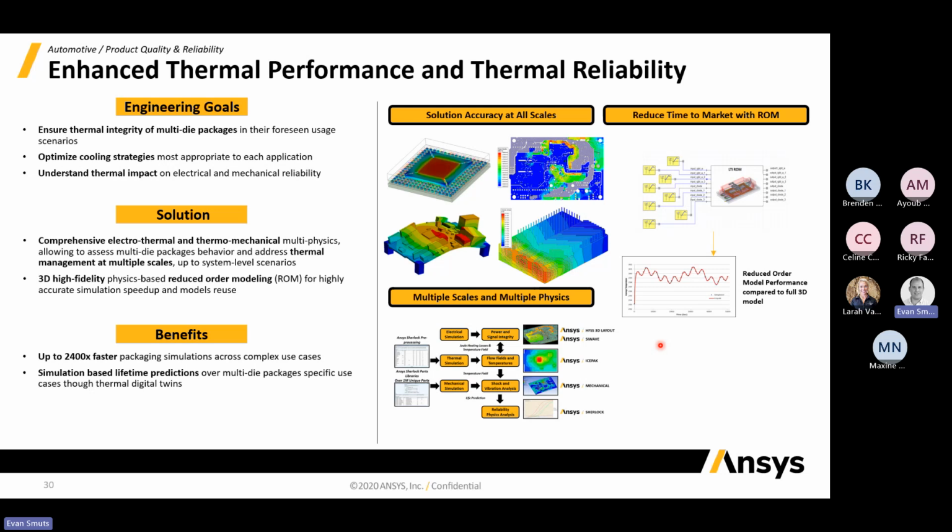And that often takes 3 or 4 iterations back and forth to get a more realistic design. In some cases, I've seen the final temperatures be as different as 20% from the original estimates, just because of this iteration and updating of material properties. So it's certainly something to consider when doing the analysis, and we have a number of automatic solutions for that kind of back and forth coupling between different physics.